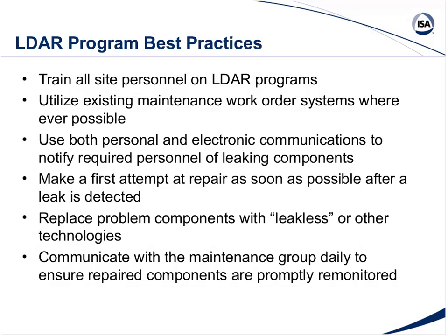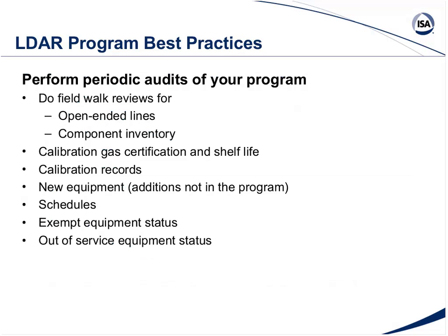We have some facilities that are out there, they're required to put in leakless technology, and you wanted to make sure that the warehouse no longer had the old kind of valve, so the guy who went out and repaired didn't put in the wrong valve down the road. So those are some things to look at. And you want to communicate with your maintenance group to ensure that repairs are done promptly and everything's re-monitored. Self-audits, there's nothing that gets around self-audits.